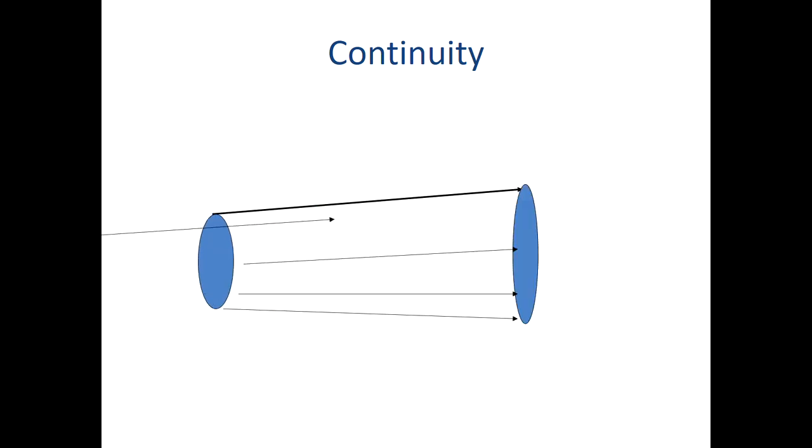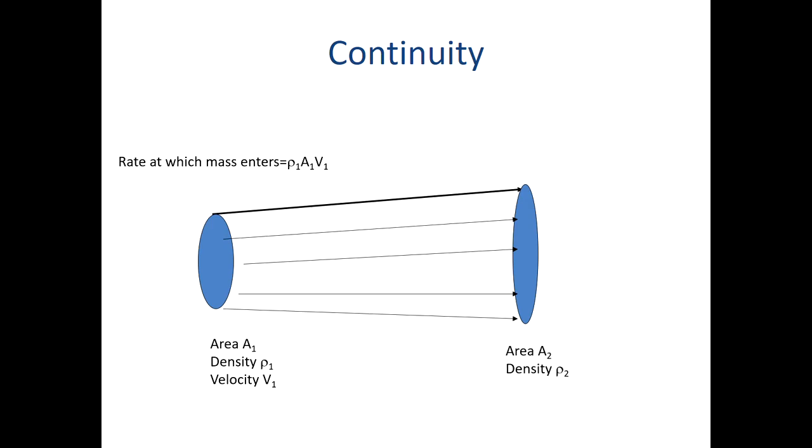So how do we express this in mathematical form? So this is the stream tube. Left side has got an area of A. In a compressible flow, density may change, the velocity may change. Remember, now we are talking about the velocity along the streamline. There's no normal to the streamline. So this is almost like a scalar. V1 is a scalar. It is normal to the blue boundary on the left side. On the right side, area has changed, density has changed, volume has changed. Therefore, the mass flow rate has changed.